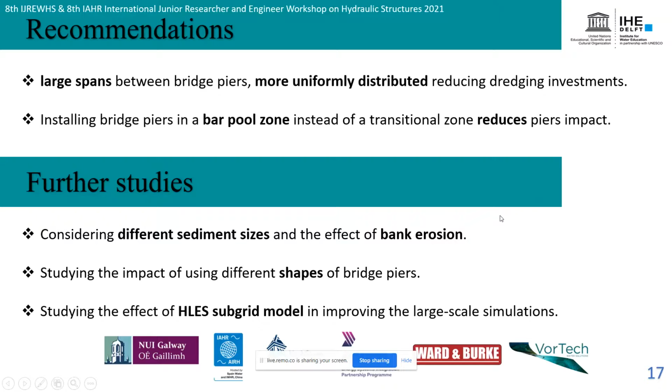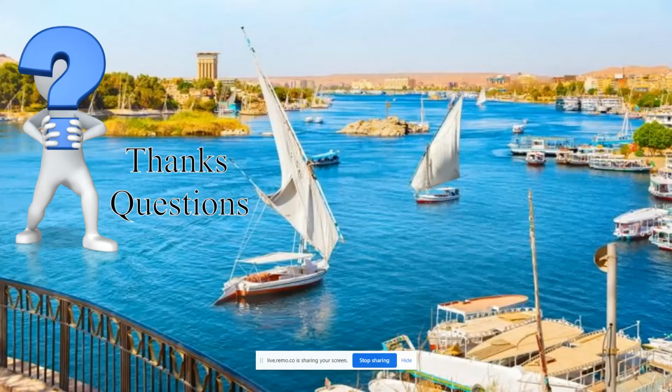Also in our study we assumed a uniform eddy viscosity and diffusivity in the Delft3D equation, but we recommend using the effect of a horizontal large eddy simulation subgrid model in improving the large scale simulation. That's all. Thank you.